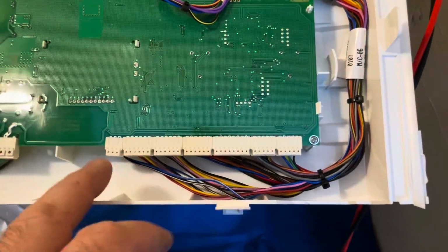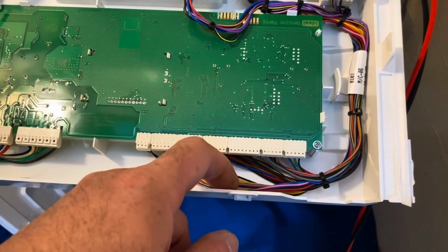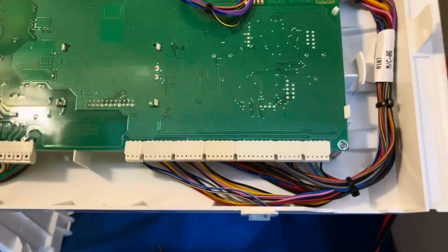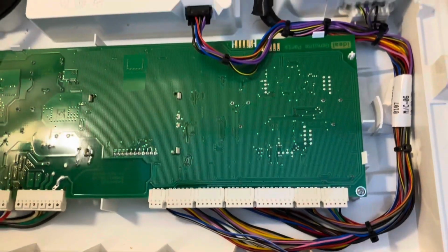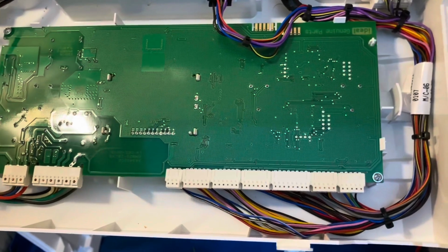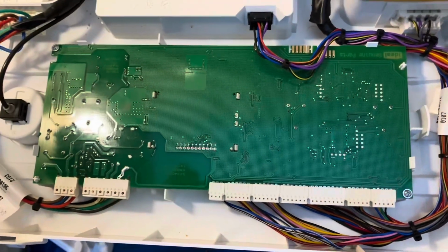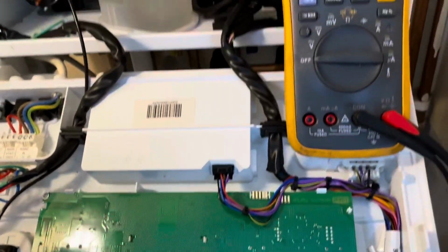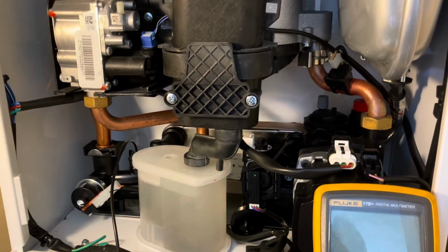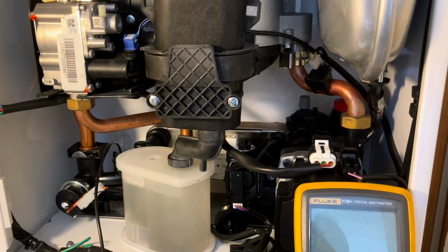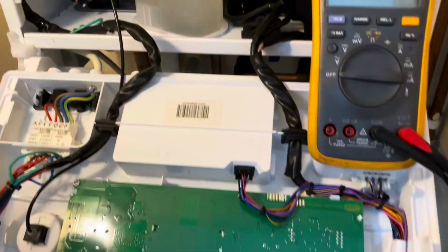And like I said, when you're doing it at the board, you're not just testing the gas valve. I'm testing the state of the harness too. So if you've got a fault with the harness, this test here will show it up. So it's good to know, it's good to do, and if you're serious about repairing boilers, I would incorporate these tests into your working practices. Okay, that's going to be me for now.